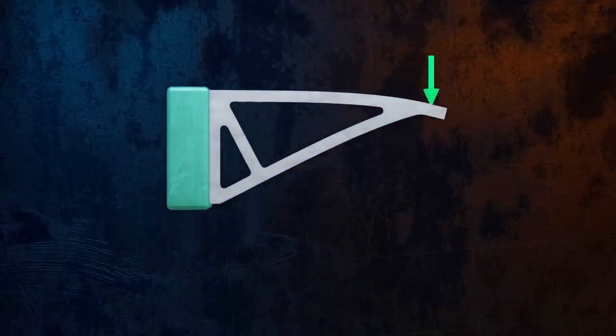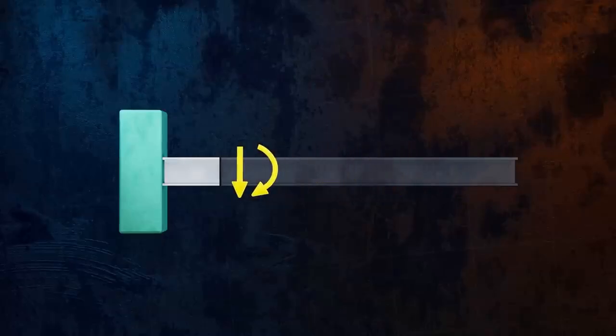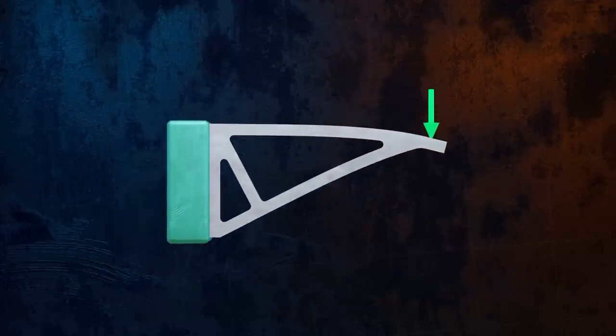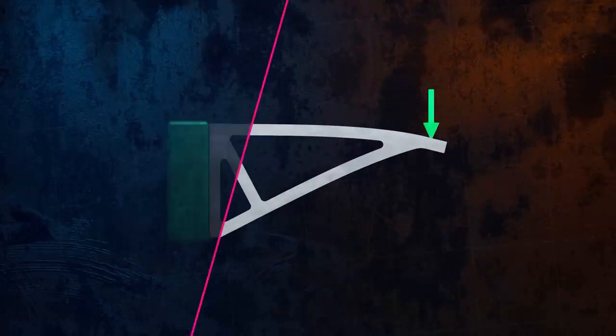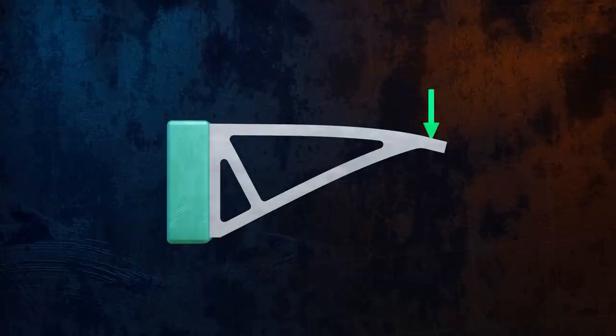This is easy to do for a simple beam. We can use equilibrium to calculate the bending moment and shear force along it, and from there, we calculate the normal and shear stresses in the beam. But enforcing equilibrium over a two-dimensional shape like this bracket is difficult, and it becomes even more complicated for a three-dimensional body. The finite element method approaches this problem by splitting the body into a number of small elements that